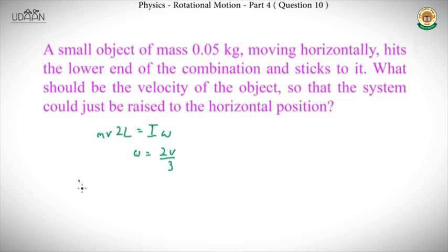Let's draw the body again over here. We have this part, we have this second part, and we have this small mass, right? If this is the 0 level, the potential energy of part A will be given by mass of A into minus L by 2 into g. The sign is important, because it's below the zero reference level.